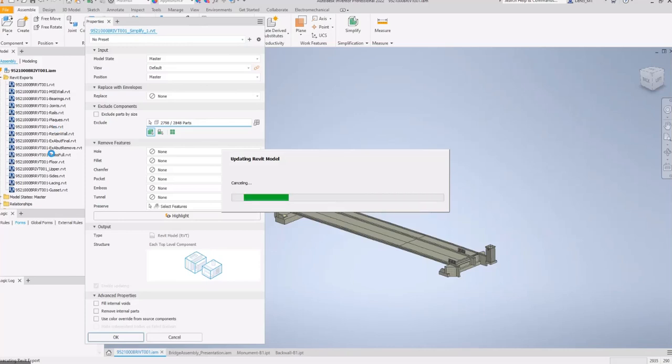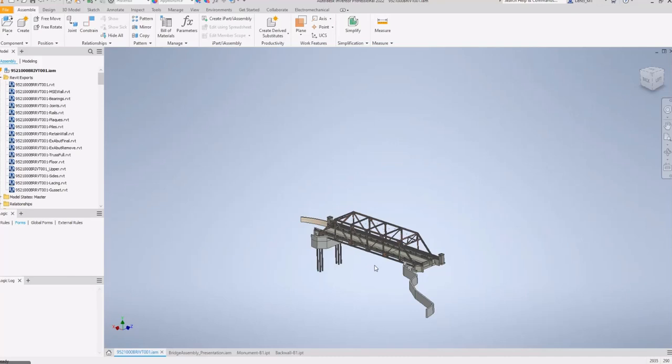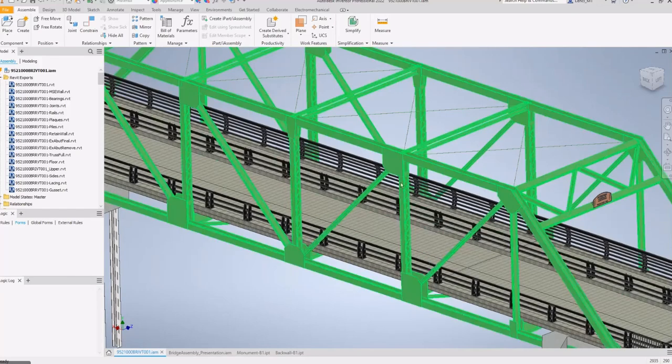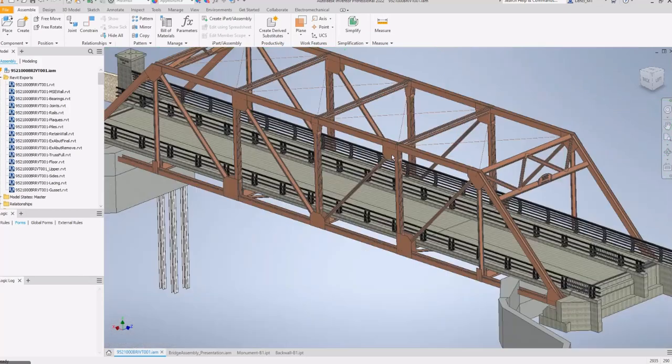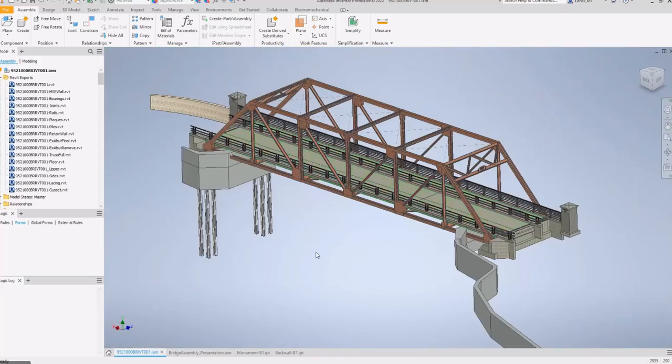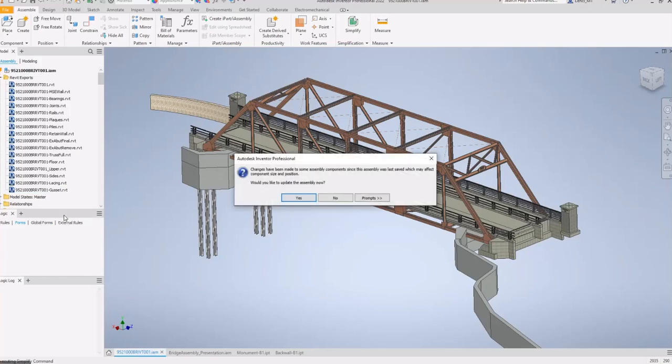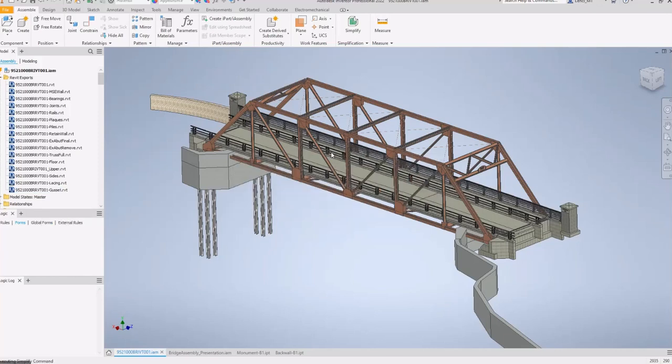And what we've found this does is it's extremely agile to be able to update even something as large as this truss. You can imagine, if I calculate the thickness of these gusset plates, we may not want to update the whole entire structure if we can just update these gusset plates. And picking on those gusset plates one more time, let me do a quick edit simplify and show that they're in their own package to be exported.